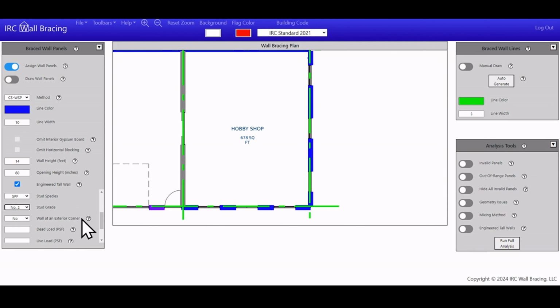This one here, wall at an exterior corner. By ASCE 7 load tables and whatnot, there's this phenomenon where wind that's wrapping around corners of the buildings, namely this panel and this panel, those panels are going to be experiencing greater pressure, so you need to design for that. I'm just going to do one of these walls here, so that wall is not at a corner.